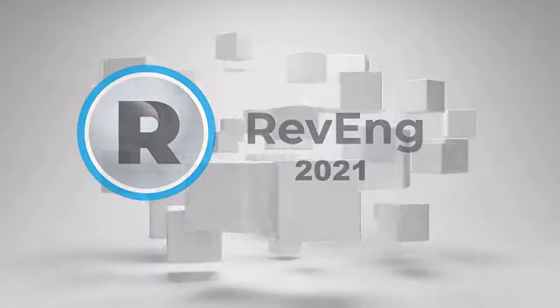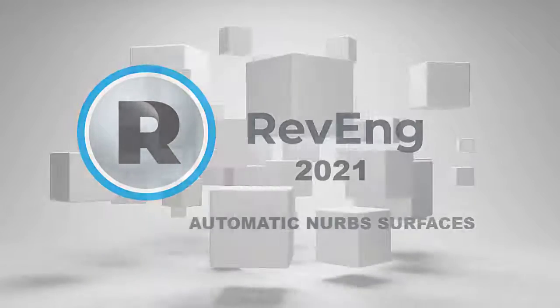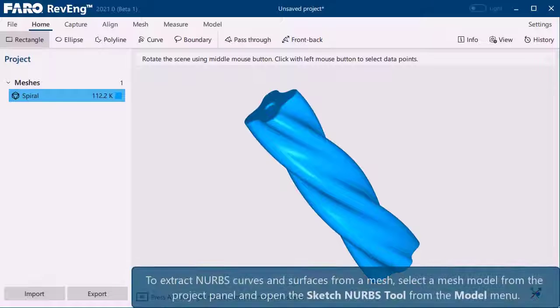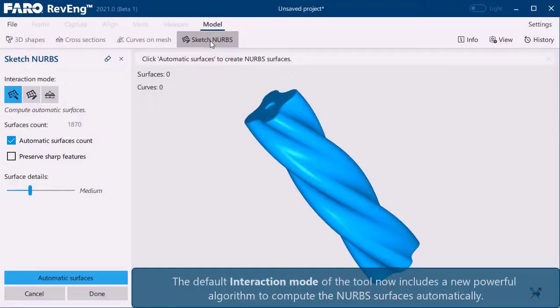With RevEng 2021, you can now generate NURBS surfaces from a mesh model with a single mouse click. To extract NURBS curves and surfaces from a mesh, select a mesh model from the project panel and open the Sketch NURBS tool from the model menu. The default interaction mode of the tool now includes a new powerful algorithm to compute the NURBS surfaces automatically.